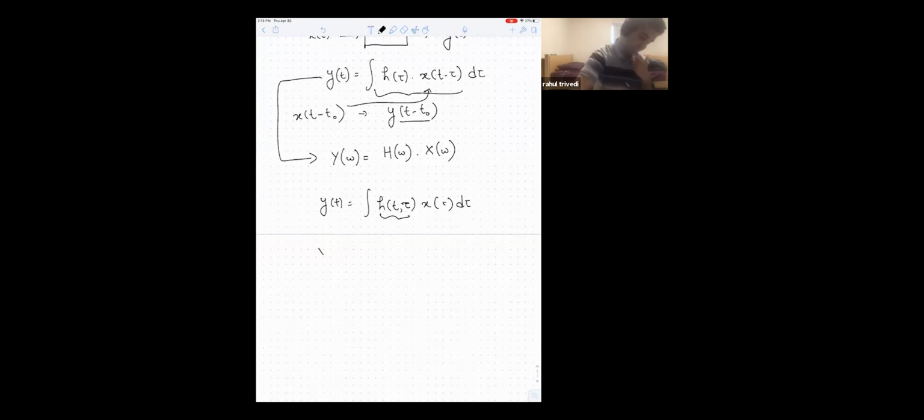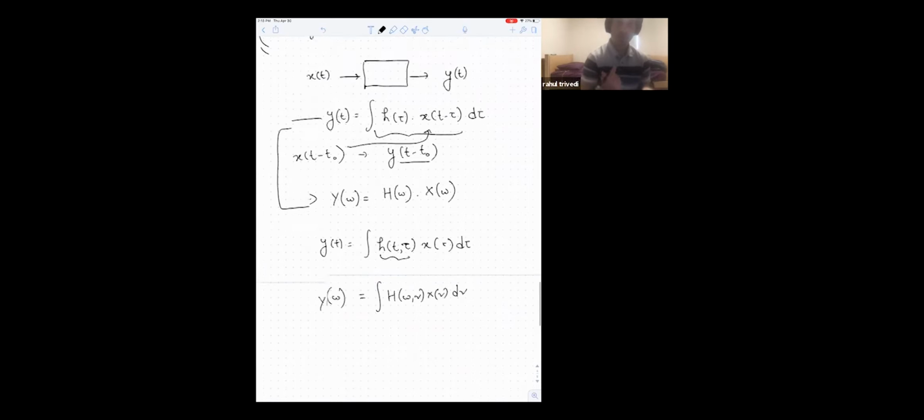And in this case, if you try and Fourier transform this equation, what you'll see is that the frequency omega would in general be affected by all the frequencies in the input. So you will not be able to get a simple function of frequency describing the response of the system, right? And the very fact that we have been thinking about our scattering matrix as a function of frequency means we are looking at a time invariant system. Okay, does this make sense?